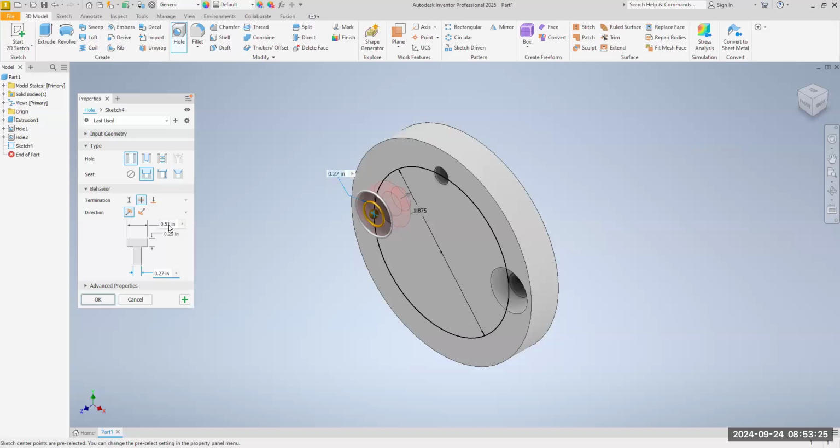What is the major diameter? What do you think, based on the drawing, the major diameter is? Are you sure? I say major, that's the largest diameter. 0.44 is the hole at the top. Okay. So we're going to hit the backspace here and type in 0.44. That is this diameter right here. Now, Stephen, what is the through hole diameter?